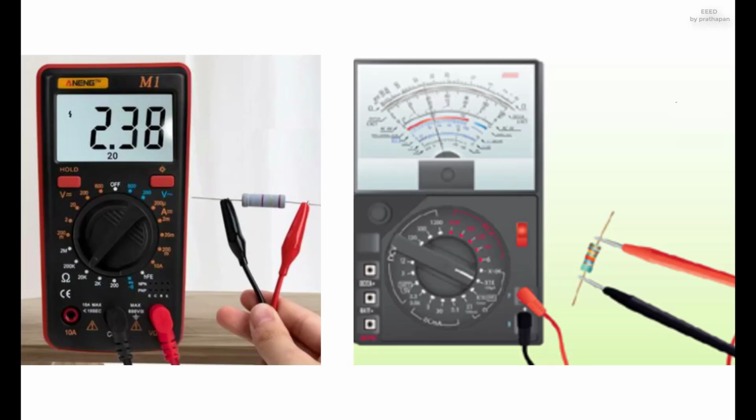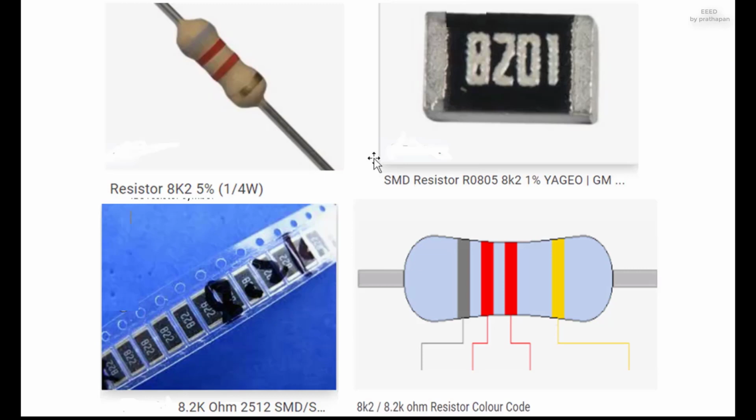The notation to state a resistor's value in a circuit diagram varies. One common scheme is the RKM code following IEC 60062. It avoids using a decimal separator and replaces the decimal separator with a letter loosely associated with SI prefixes corresponding with the part's resistance. For example, 8K2 as part marking code, in a circuit diagram or in a bill of materials, BOM, indicates a resistor value of 8.2 kΩ.